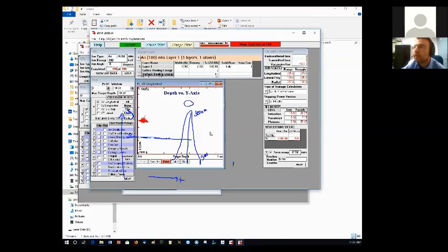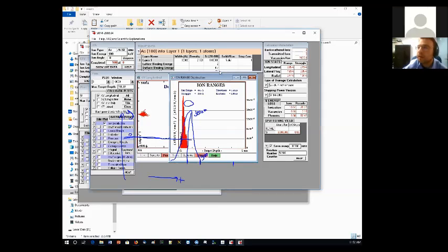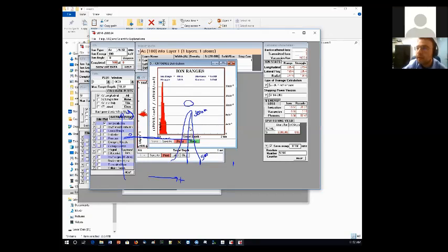Yeah, it's very tiny, right? We know the reason: because it is a heavier ion, it will be stopped a lot earlier because it's going through nuclear stopping rather than electronic stopping. It's not interacting with the electron cloud, but it's interacting with the crystal itself. If we look at the ion distribution, now remember this was the other graph, so let's bring it.